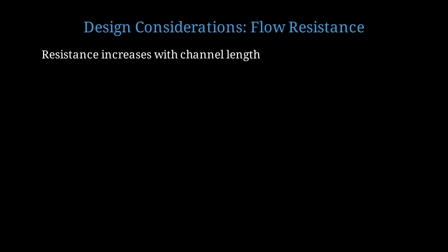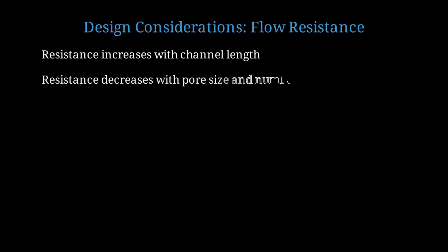Let's get technical about flow resistance, a critical design parameter. Flow resistance increases linearly with channel length. Longer channels mean slower flow and lower capillary pressure at the end. Resistance decreases as pore size increases and as the number of parallel pores increases. Wider channels have lower resistance.